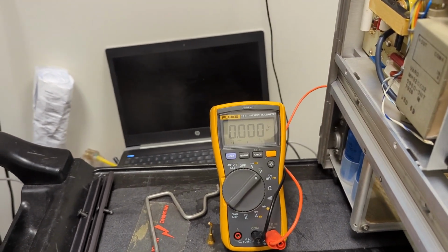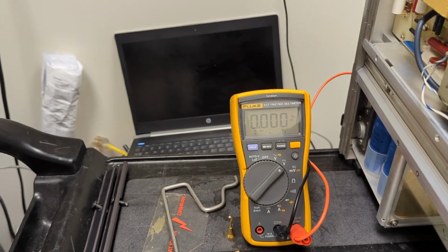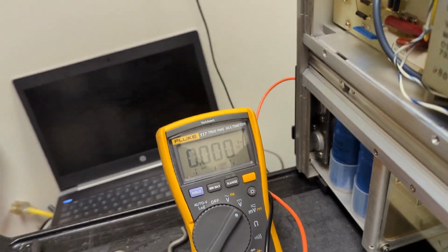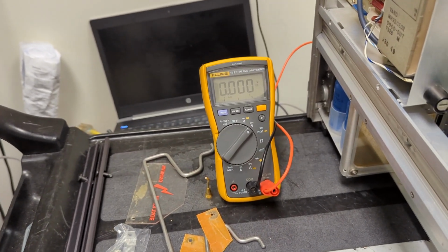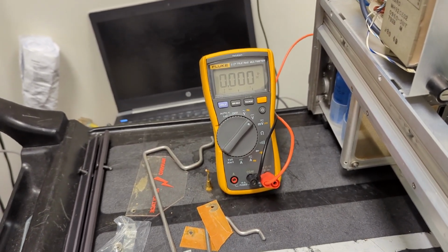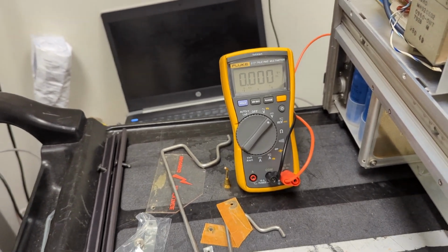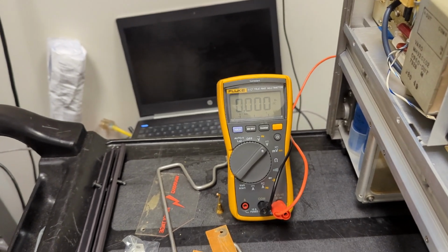I did do that for the high voltage board, and I did check the -3 kilovolt test point. We got about -3,200 volts, which is pretty much where it should be. That was without the CRT connected as well, which might explain why it's a little bit higher than it was before.